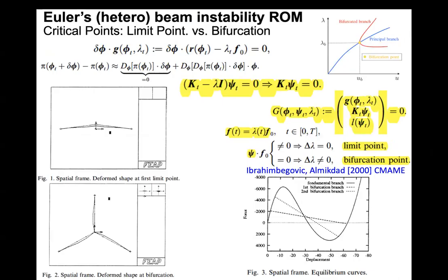There's also the point of computational instability. Now I haven't discussed this in detail. You have it in chapter 8 in the beginning. This is one part that I never touched, but I can do it now. Basically, when you have instability with, let's say, large pre-buckling displacement, the condition is always the same. Your tangent stiffness matrix becomes singular. Your lambda, the eigenvalue that corresponds to this one, becomes equal to 0. And then psi here is your corresponding critical mode.